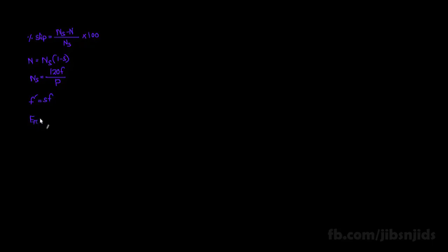At running condition, induced EMF per rotor phase will be equal to the multiplication of slip and standstill rotor induced EMF per phase. Besides, rotor reactance per phase under running condition will be equal to the multiplication of slip and standstill rotor reactance.